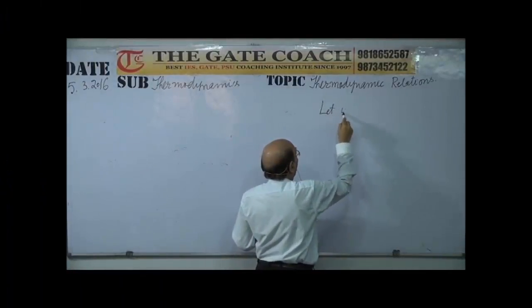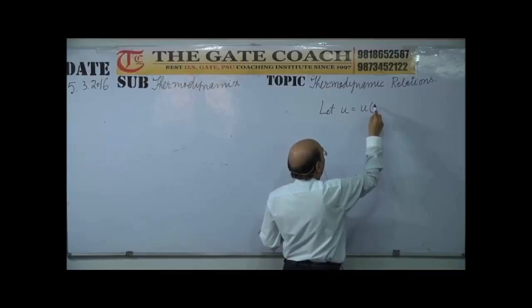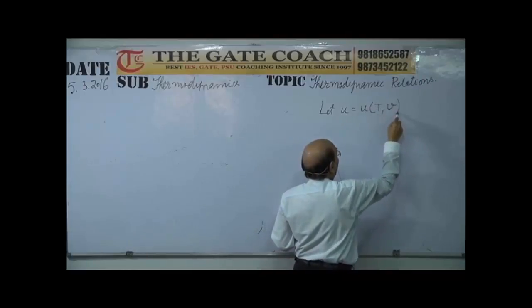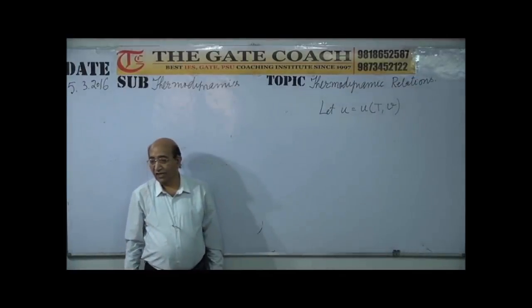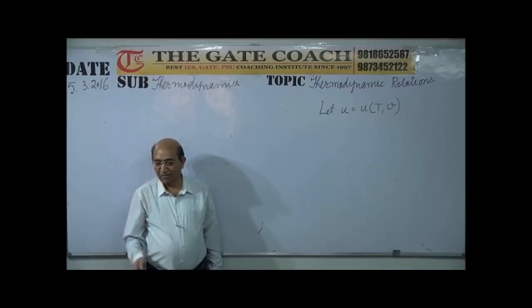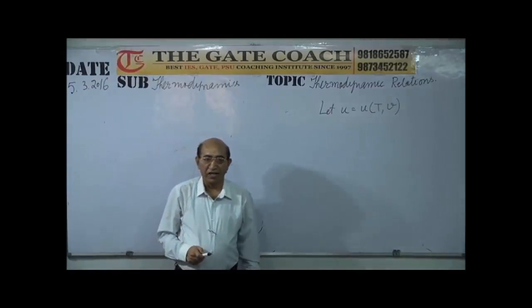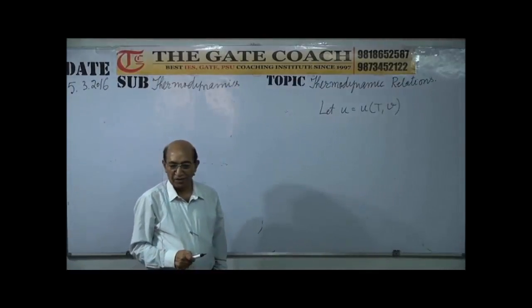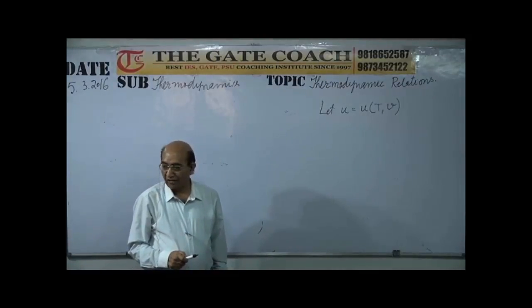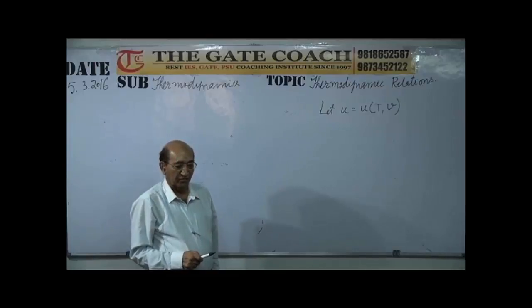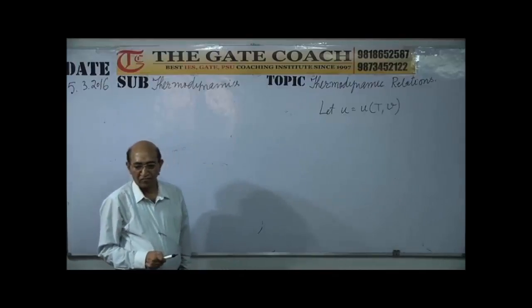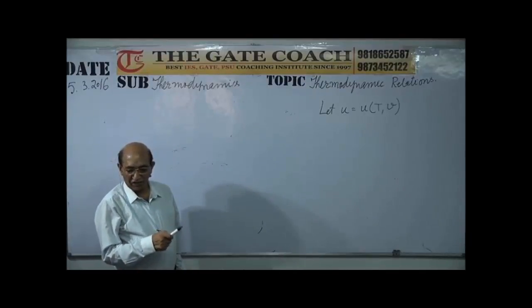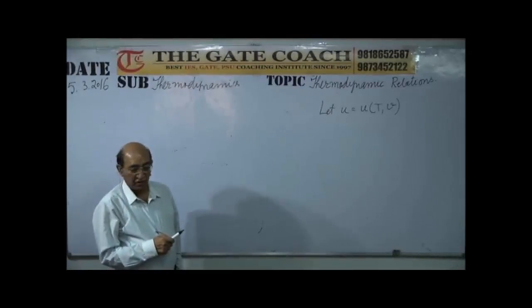Let internal energy be a function of temperature and volume. And then I will prove that it is not a function of volume. Same way again I will proceed and prove that internal energy is not a function of pressure. And finally, it is a function of temperature only. This will be for an ideal gas. And then same way we will start discussing about the real gas.